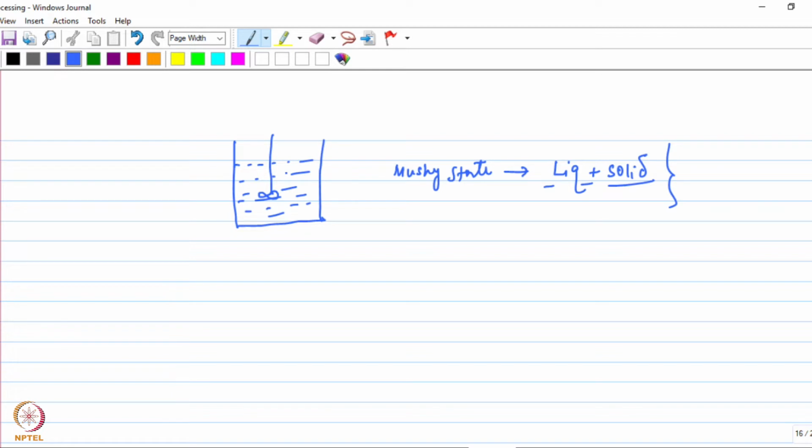So when the particles are added, these particles will be mechanically entrapped and will be prevented from agglomeration. Okay, so you can expect a better particle distribution in this case due to the presence of the solid when the particles are added into this two-phase material. Okay, so as the particles are added, the solid ceramic particles will interact with this two-phase material and a bond will form, resulting in formation of a composite.